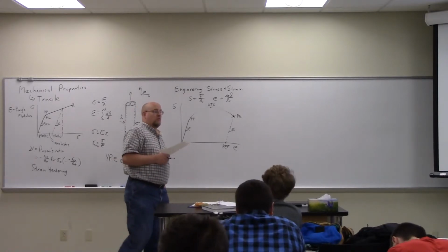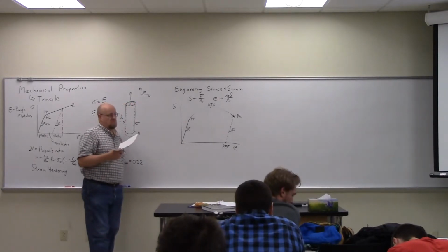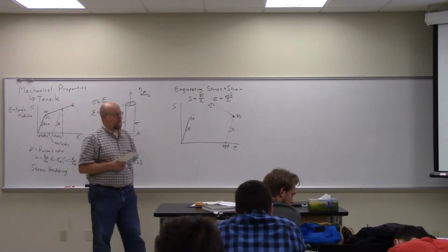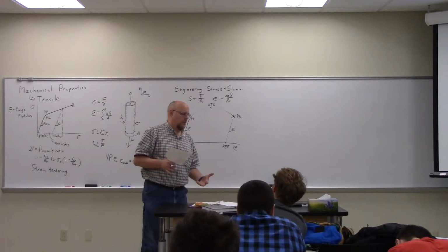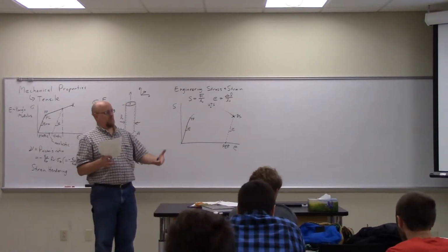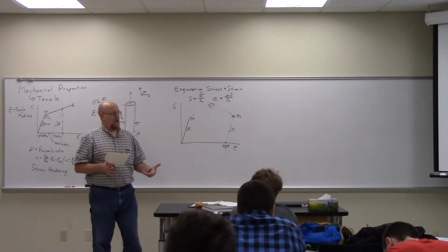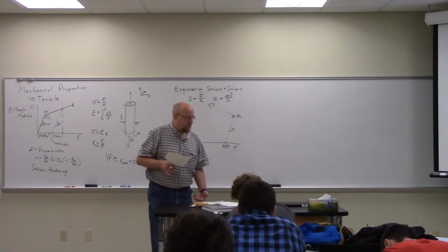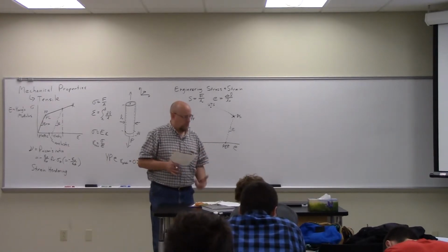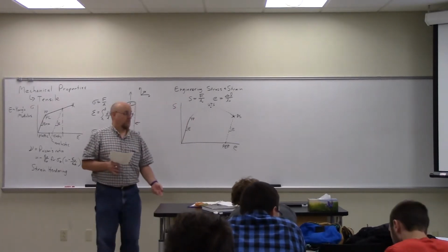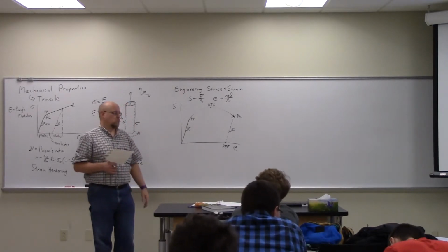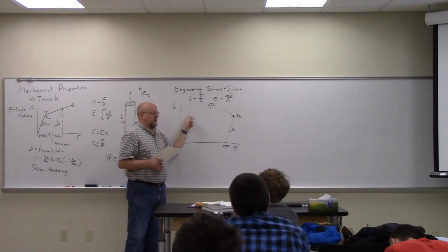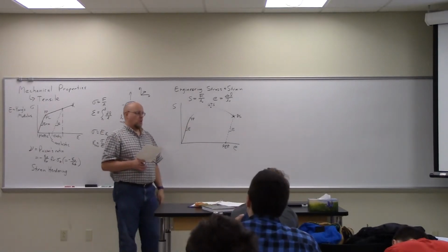So deflection of a beam is, in theory, not permanent, right? Deflection of the beam resulting from a load, if I step off the beam comes back, right? If it bends, then that means the beam is permanently deformed. I step off, it comes back a little ways, but it's not straight anymore. Okay, so you're just talking about after the yield point in this context? Right. I thought you were saying over the whole thing, but yeah, I got it.